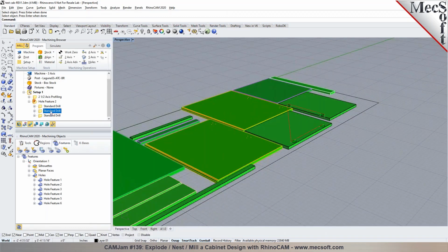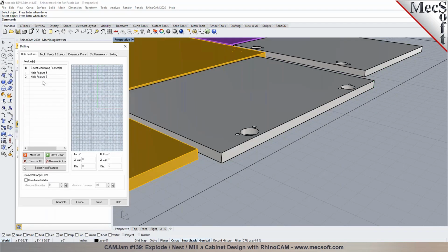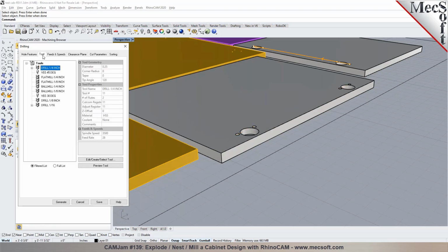Cool. And then for these holes that you have, these are larger holes. And you can see the hole feature, it says 0.3125. There's 2 holes, they group them together. So you can use a 0.3125 drill bit. So it says the closest drill we have in the library that's close enough to 0.3125 is a 1/4 inch, because my library did not have a tool that matched it.